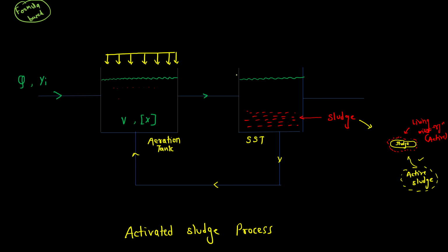Okay, now when the sewage is initially brought to aeration tank, there is aerobic reaction. Sludge is developed. That sludge is settled in the secondary sedimentation tank. To increase the efficiency of this process, some sludge is taken back to the aeration tank. So when it is taken back, let's say the discharge is QU. I'm giving some notations here, so you just write it down. A certain amount is taken to the sludge digestion, that is, it is wasted. So it is a waste sludge